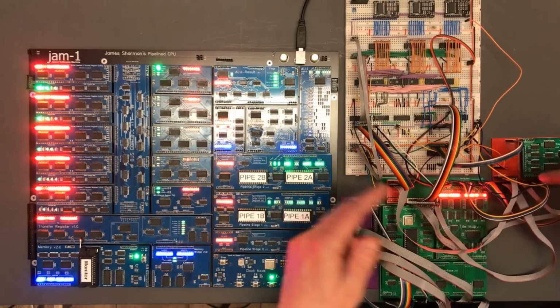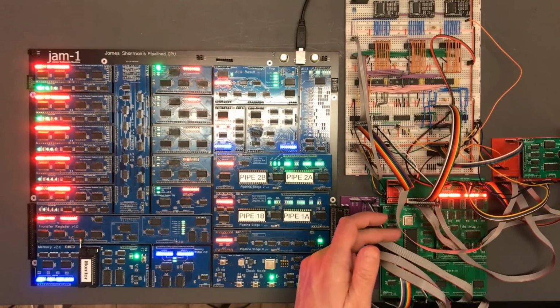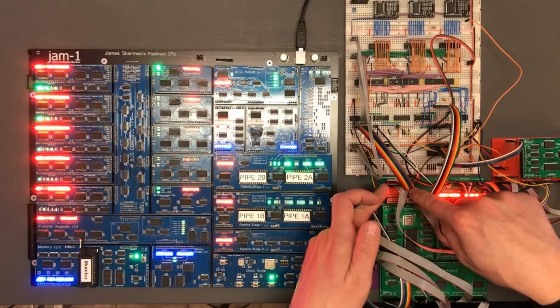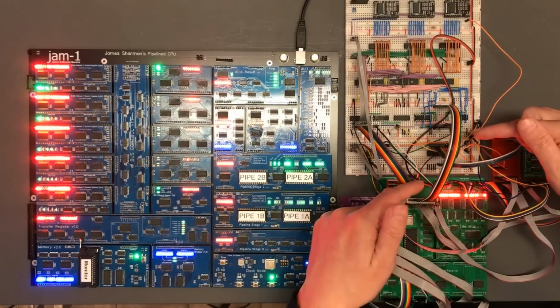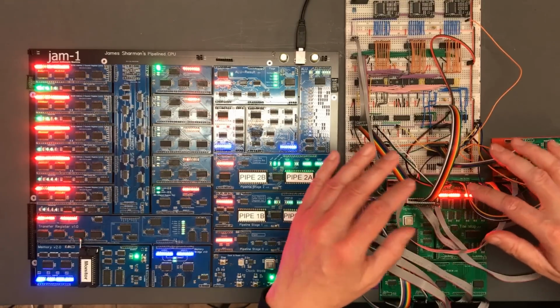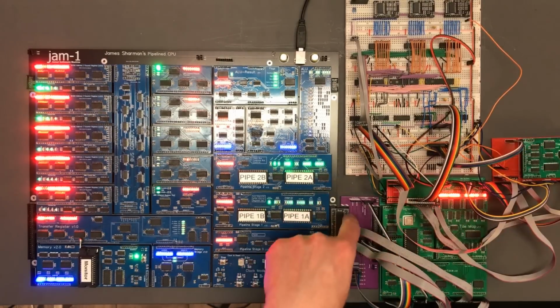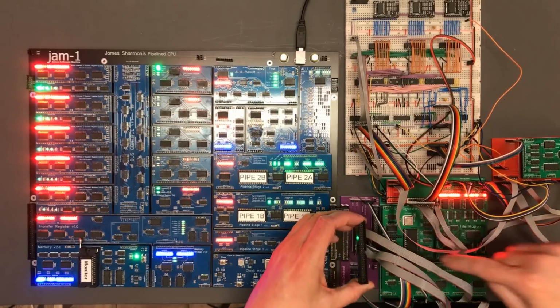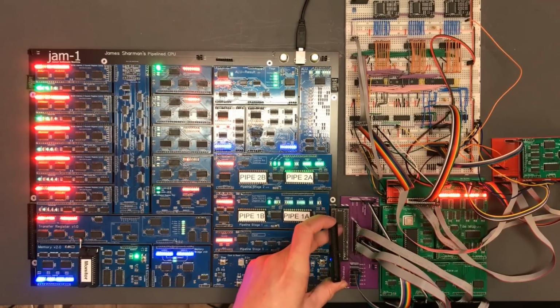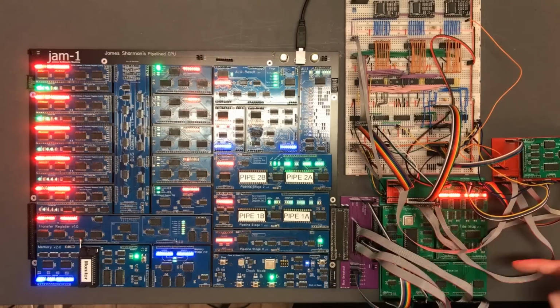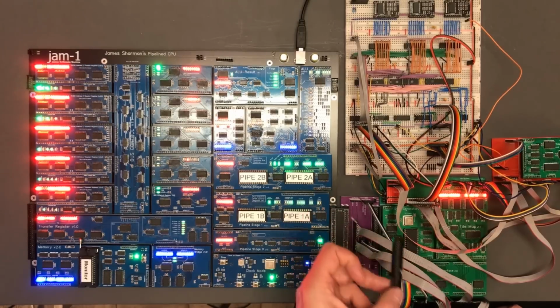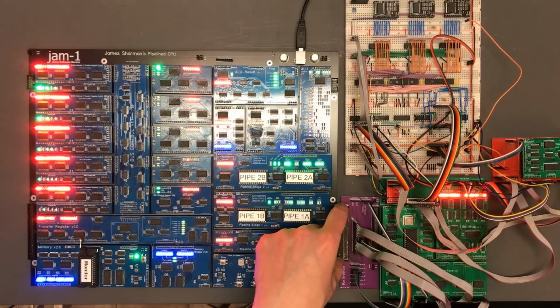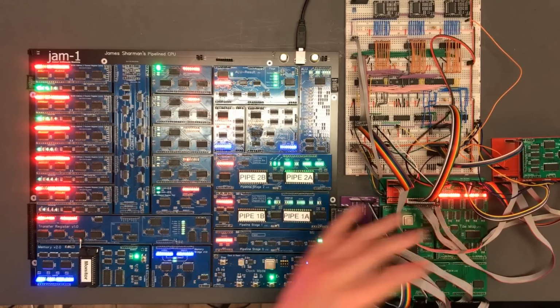And when we started to expand this beyond the tile data we added, I ended up having to create some kind of doubling breakout PCBs to give me enough connections to the mem data and the address bus. And all of that is problematic, and that's added to the problem we've got. Now the bus down here has got all of these connections on the side here. We hadn't defined this bus and this breakout board at the time when I defined this backplane, but if I had, what I could have done is stuck one of these bus connections on the side, and then with just one of these little bridge connectors we could have made all of those connections in one go.